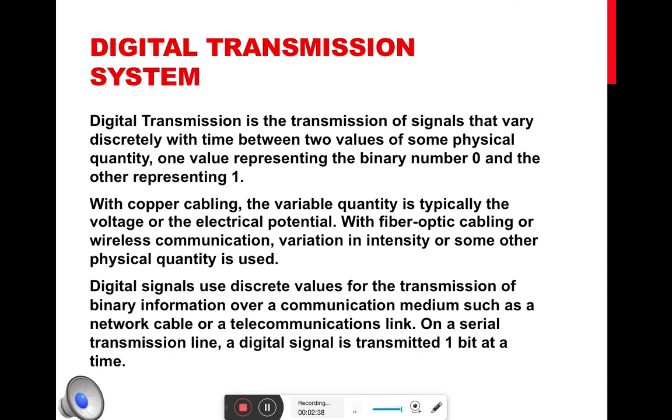This optical intensity variation can be modulated and then transmitted through a communication medium. Similarly, at the receiver side, this optical intensity variation should be detected by an optical receiver, and the corresponding decoding has to be done, and the signal can be extracted.